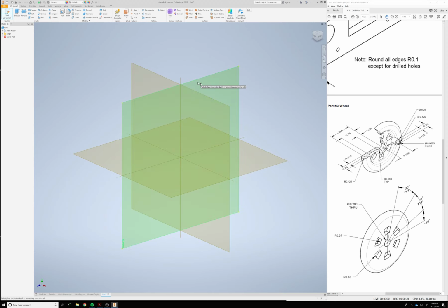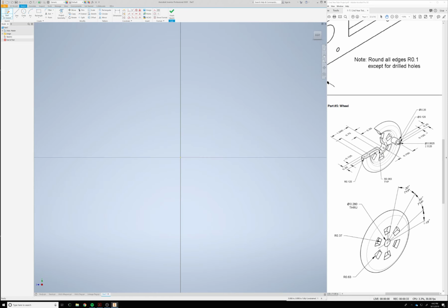We're going to create a new sketch on the YZ plane, and let's just go ahead and start sketching. I'm going to start out here, out in the middle of nowhere. I'm going to come back to directly above the origin. That is our center hub. Okay, going to go straight up, out, down, in, down, out, and down. Okay. And then I'm going to use my coincident constraint to lock this in with this.